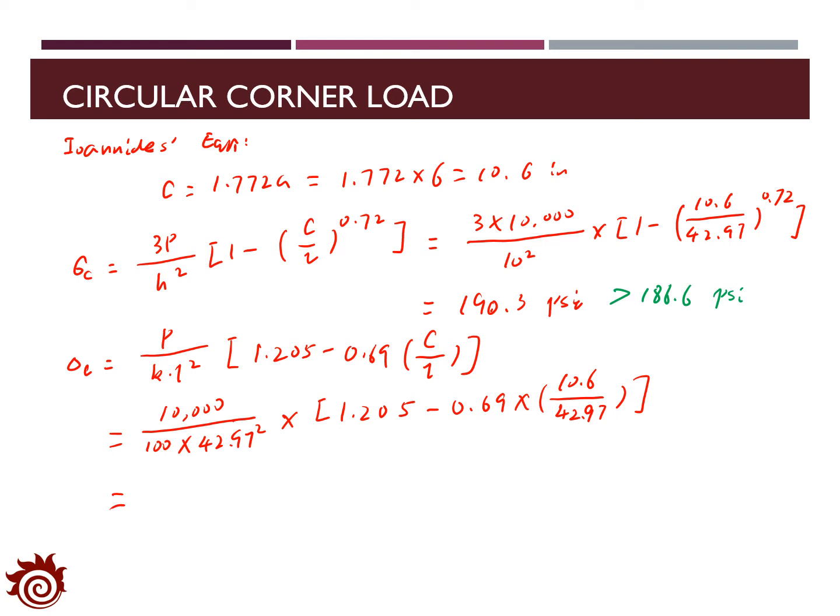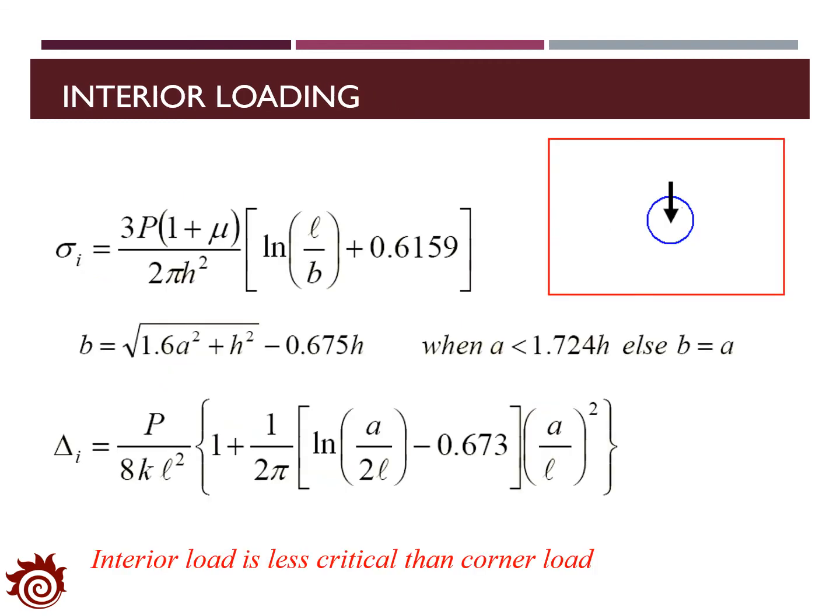With that, we can find out the deflection as 0.0560, which is also higher than the one we calculated from the Westergaard's equation, 0.0502. So that's the way for us to find out the maximum stress and deflection for the circular corner load.